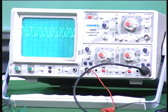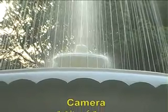So, thus we have seen in this lecture 3 different types of oscillator circuits built using op amp. One is the RC phase shift oscillator, the other one is the Wien's bridge oscillator, and the third one twin T network oscillator. All the three are very useful, but the most useful among them will be the Wien's bridge, because it is much easier to vary the R and C components. You can have ganged resistors and ganged capacitors, and you can vary the thing. Most of the oscillators that you get commercially in the low frequencies less than 1 megahertz are based mostly on Wien's bridge oscillator. Thank you.